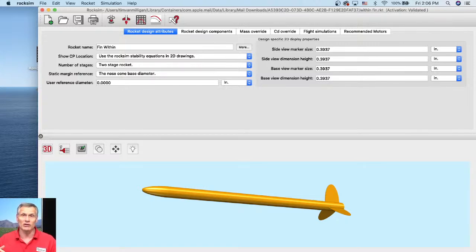And then the second part is the strength of your rocket depends so much on your own building skills. How you attach the fins. It's not only material, but it's how you do things. Are you going to put fin fillets on? This one doesn't have very big fillets on, and it's a surface mount. If I put fin fillets on, it's going to change things immensely. So then we have to figure out how much strength does a fin fillet add? And then how big of a fin fillet? So it gets really complicated really fast.